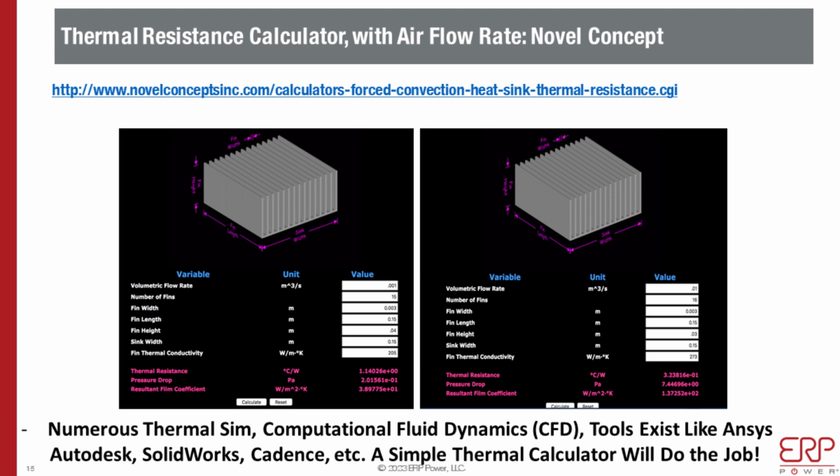Right at the top, notice there's an airflow. I don't know, this might be a little bit of an eye chart, but the main thing that I changed from the left to the right is the airflow, essentially increasing the airflow. And I also shortened the fin size, so that's another thing that I changed. Essentially, the thermal resistance goes from 1.1 to like 0.3. So like 1/3 of the thermal resistance just by increasing the airflow.